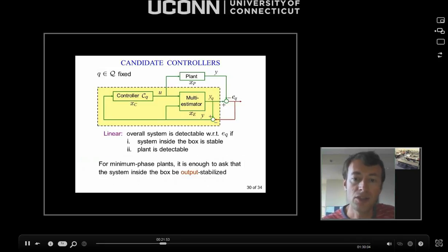There are also relaxations where, and this is quite a standard assumption in adaptive control, you strengthen detectability of the plant to a minimum phase property. In the linear world, that would be that the zeros, or transmission zeros, of the plant are in the left half plane. There are also nonlinear versions of the minimum phase property that we have been working on.